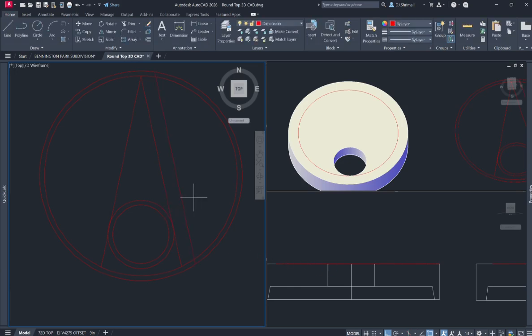I don't like the narrow cursor, because using that cursor I have to zoom in more and select the line one by one, or it takes a little bit more effort for me. So I just like the bigger cursor so that I can click it quickly. And now I'm using the trim command, so I like using TR enter, and then if I need to extend I press shift along with that, so that I can extend and trim at the same time however I want.